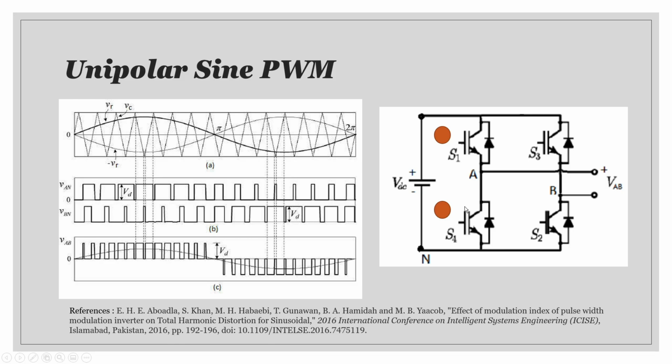So I will turn on S4 here, complementary with S1. So the freewheeling current will go through the S4 MOSFET instead of its diode. S1 and S4 will be complementary pulse width modulation at high frequency, and then S3 and S2 will be modulated at the fundamental frequency, maybe around 50 or 60 hertz. So this will be slow switching, and this will be fast switching.